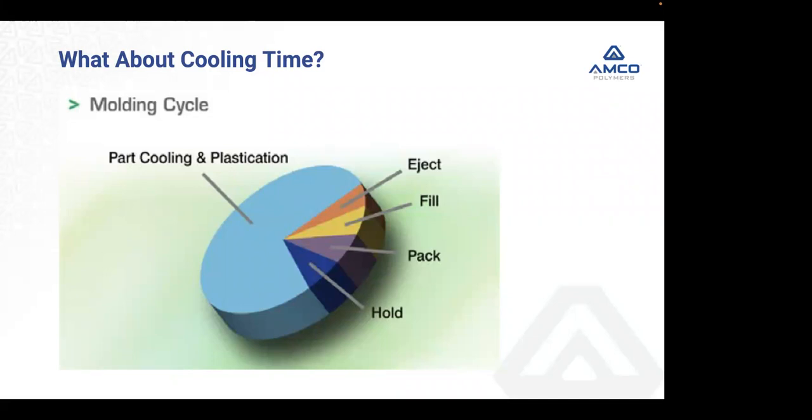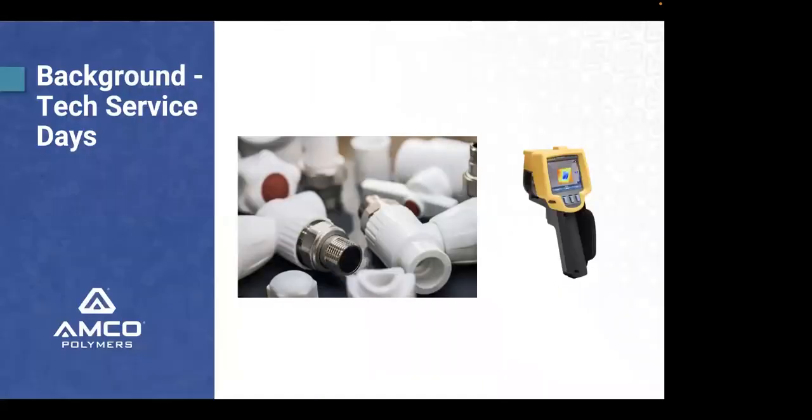So basically you fill it, you pack it, you hold it. Everybody does scientific molding, systematic molding, decoupled molding. Everybody knows and understands your viscosity curves, gate freeze, and so on and so forth. But one thing that's really not discussed or covered is part cooling and plastification. As you can see, cooling and plastification is probably 80+% of the cycle time, and yet it's typically ignored. And there's really not a seminar or class that you can go to on this. So I dug into it and said, okay, what can we do?